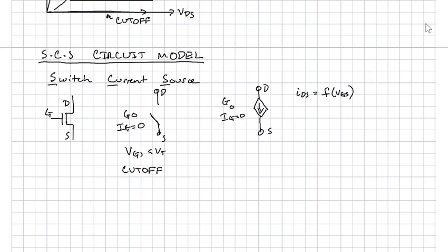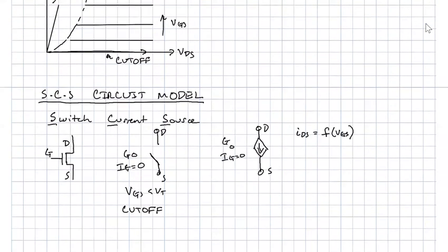That's our statement that says it looks like an ideal current source: as long as we're above that saturation cutoff, it doesn't matter what VDS we put on, we still have an infinite resistance and the current does not change. So it's only a function of VGS and not a function of VDS. And the actual function is k/2 (VGS minus VT), squared.